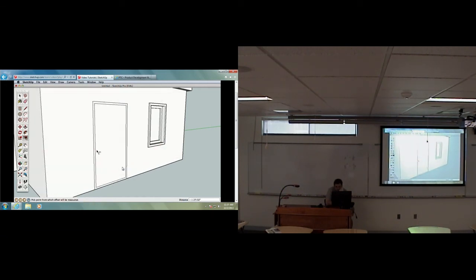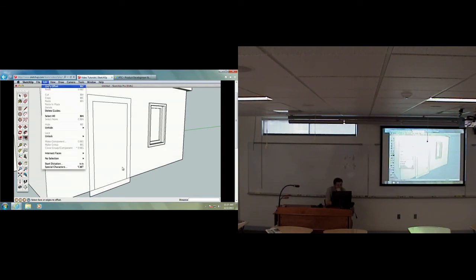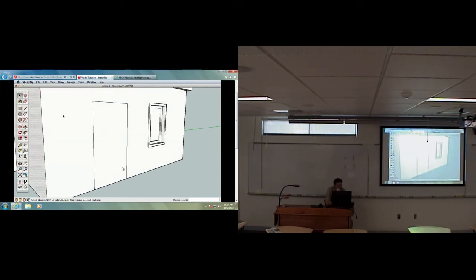Offsetting the door creates some extra geometry that we don't need. It's easy to erase these extra edges, but there is another way to use offset that will solve this problem for us. Undo back to our simple door. Use the Select tool to pick one door edge, then holding the Shift key, add the other 2 edges. With these edges selected, the Offset tool will focus and only work on those edges, so we don't have any problematic edges below our house and can correctly create the door frame. Pull the door frame out so we can use it in our next example.